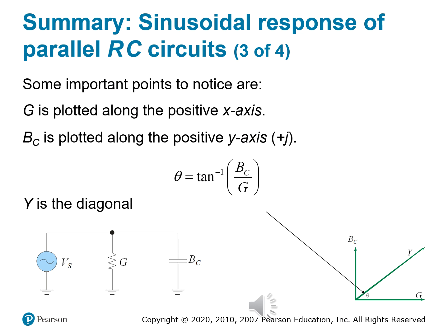In our inductor triangle, current lagged, but with capacitors in the mix, current leads, right? Same math, different orientation. And this is important because when you're sketching this triangle, you immediately see the magnitude of the admittance, right? Denoted by Y. You know how much phase difference exists, and you can predict how your circuit will behave just at a glance. It's like reading the energy dynamics of your circuit off a map.